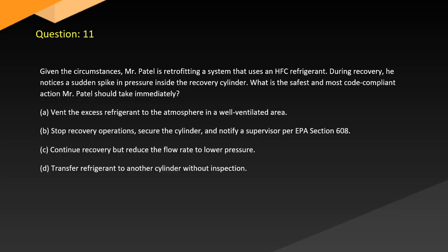Question 11. Given the circumstances, Mr. Patel is retrofitting a system that uses an HFC refrigerant. During recovery, he notices a sudden spike in pressure inside the recovery cylinder. What is the safest and most code-compliant action Mr. Patel should take immediately? A. Vent the excess refrigerant to the atmosphere in a well-ventilated area. B. Stop recovery operations. Secure the cylinder and notify a supervisor per EPA Section 608. C. Continue recovery but reduce the flow rate to lower pressure. D. Transfer refrigerant to another cylinder without inspection.